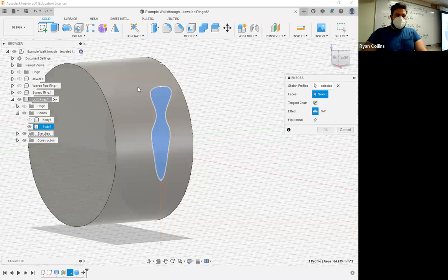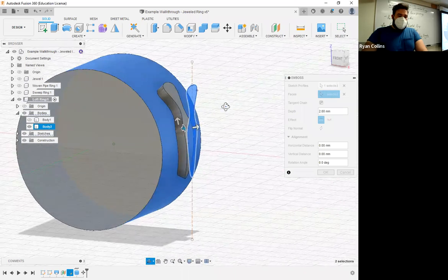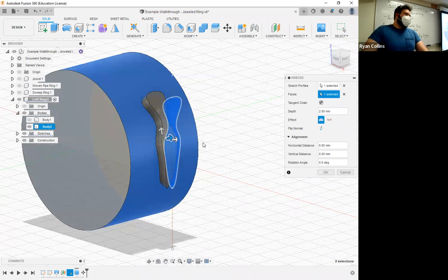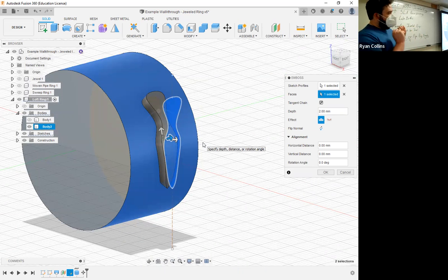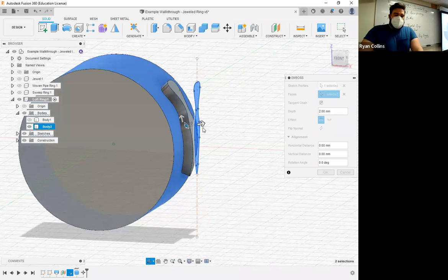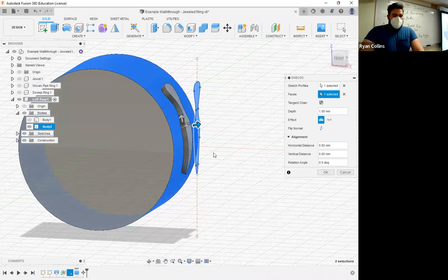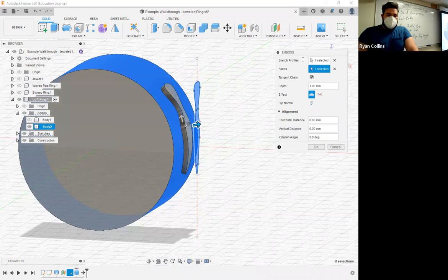Now the faces, there it works. And basically what emboss is creating is a rounded extrude off of a curved surface. We've so far used extrude as a flat sketch and flatly pulled it in one direction. This basically allows it to go in all directions off of a curved surface. So there are some combination ways you could make this work, and I'll go over that with you, just so you can see what I'm talking about with emboss.